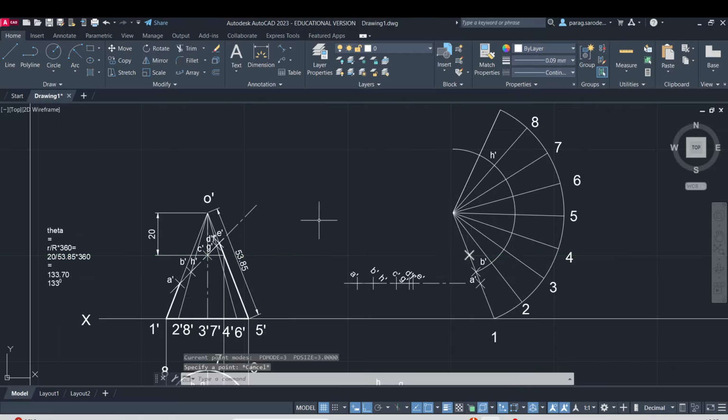So this point is for C and G. Let us transfer the D and F. This is for D and F. Let us transfer the E, and then we will transfer those points respectively on their respective edges. So let us take this R command, start and radius, take the center point in this case. So this is our reference point, and let us click it on this. So this is what we have created for C and G.